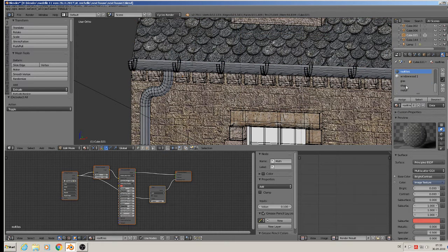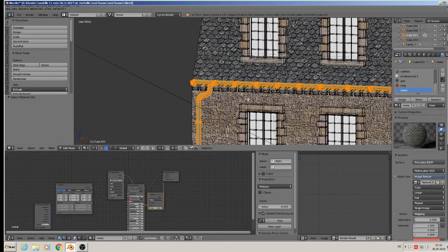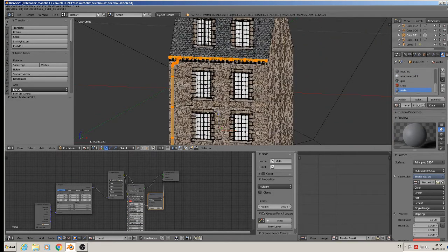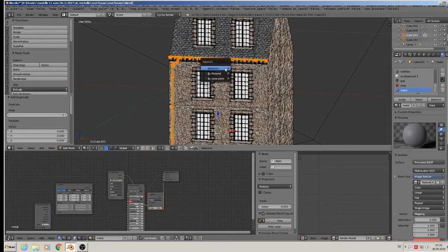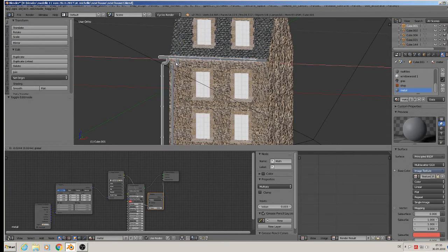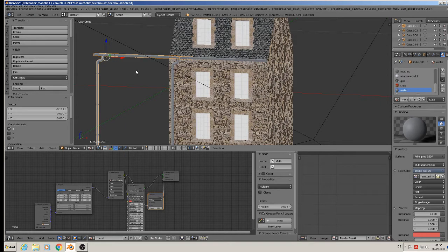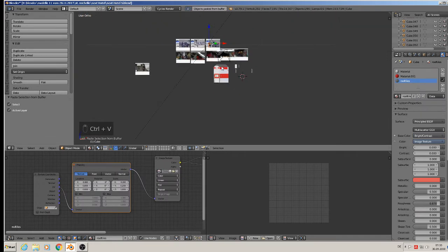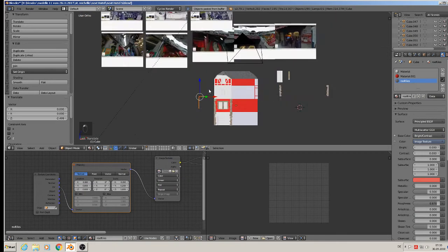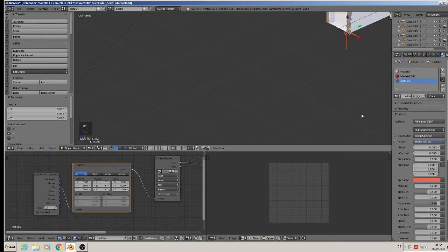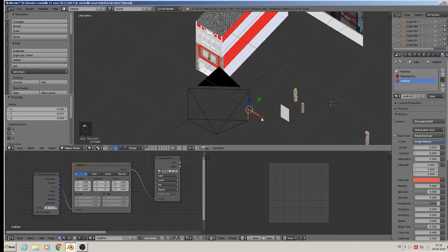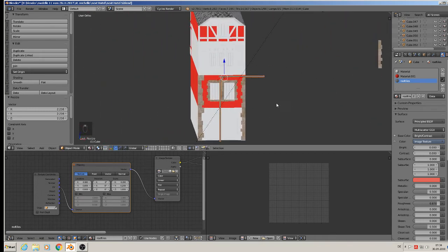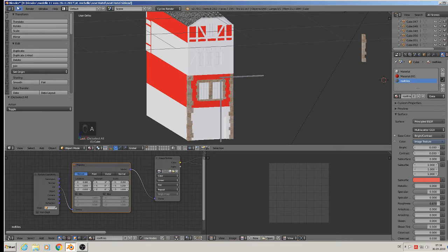So we simply say metal should be selected, then Shift D, make a copy, P to separate the selection. Now I have the candle. Control C to copy and go to the other project, Control V to paste, and it is there. For objects you can use copy, and for materials and such you can do it with append or link.